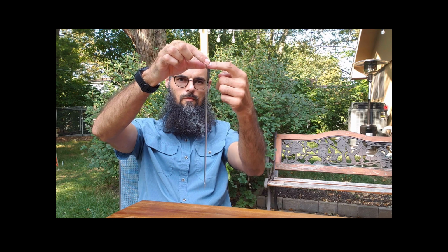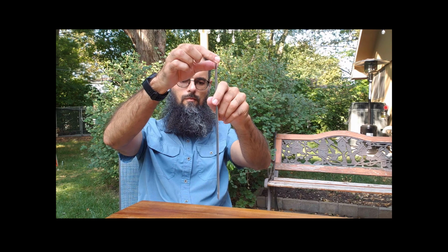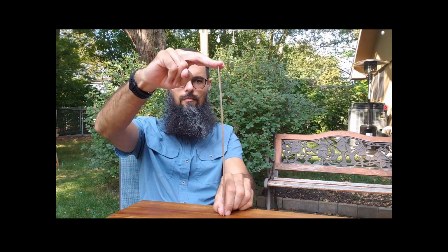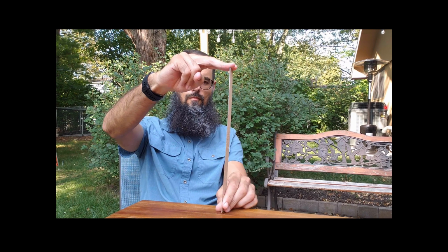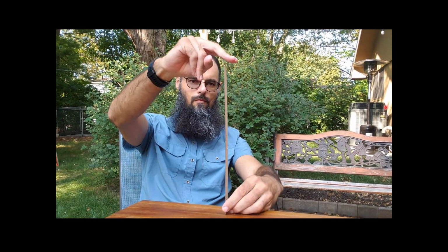But what if we constrain it against horizontal movement, but not vertical movement? So we allow the pin joint to slide up and down. So this would be a pin-pin boundary condition case where we have freedom for rotation, top and bottom, but the bottom also has constraints on translation. So what did I just do right there? Let's see, go back to this video.